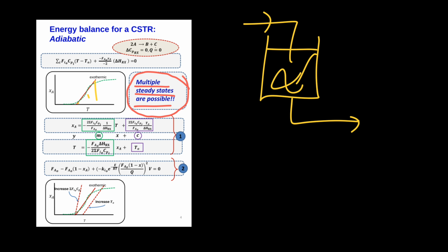It does happen that you get systems for which the mole and the energy balance look like the ones depicted in this figure, where it can actually operate at multiple steady states. And that can depend on where you start up. So startup of that CSTR will then be very important. Do you approach it from a colder temperature? Do you approach it from a warmer temperature? It can actually achieve either the high or the low steady state. The steady state in the middle is generally unstable.